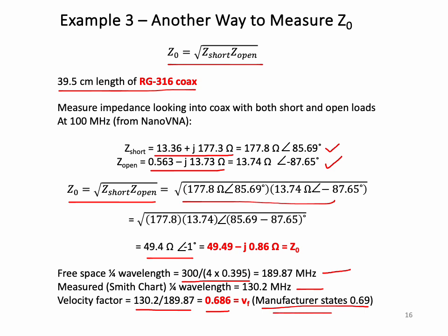Again, these velocity factors are the important parameters, not so much the Z0. It's important for the cable that's driving the antenna to perhaps be 50 ohms, but in general, what's really important in designing the J-poles is to know what the velocity factor is for the various pieces of coax used.